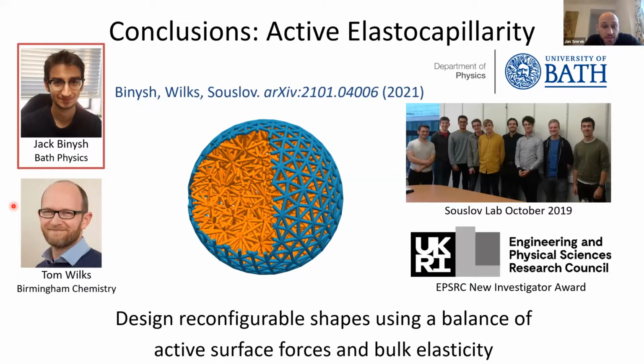I had actually a related question, and it was about these surface springs. What role does the initial triangulation play? Because I saw in your video that, especially in these pancakes or worm shapes, there are regions where there are extremely stretched bonds and others where it's not. For a different initial triangulation, you might even get a different shape, but definitely a different distribution of these stresses at the surface.